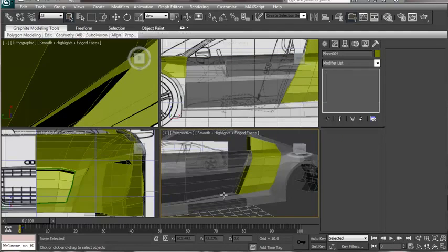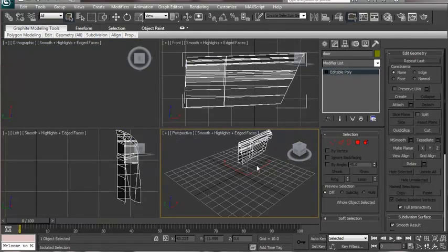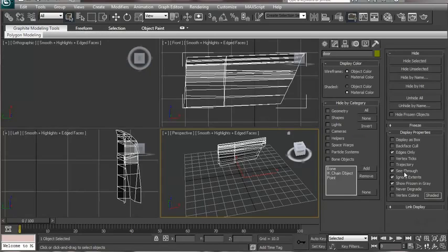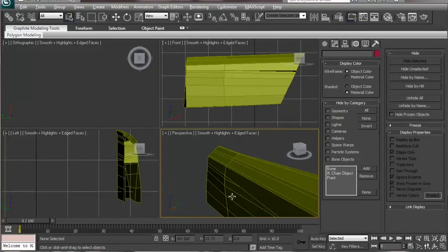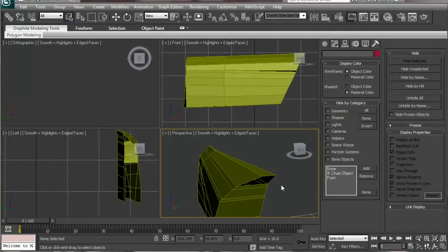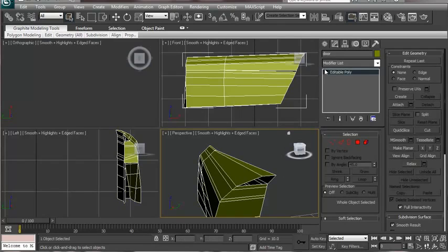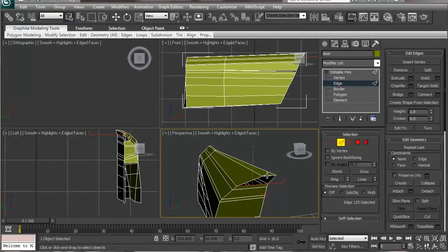And let's see if we have selected the right pieces. Let's isolate the door by pressing Alt Q. And let's turn off the see-through mode. And yeah, we haven't selected one piece of geometry over here, I think. So let's go ahead and bridge that over there. Select the geometry, go to the edge mode, select these two edges, and let's bridge them across.